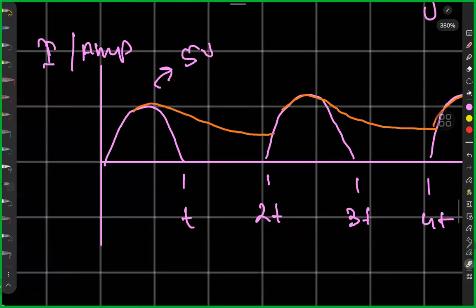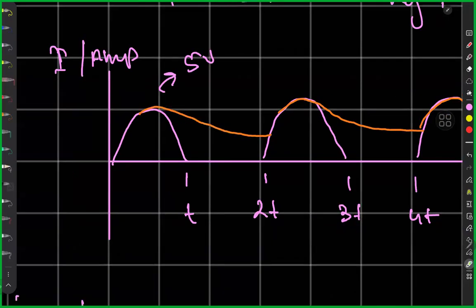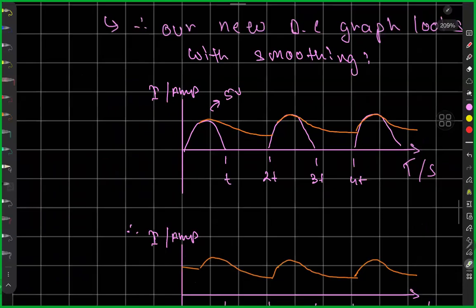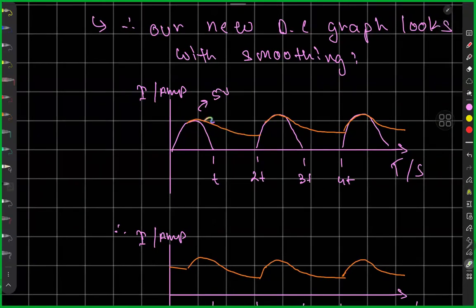And by the way, you will look at this graph and wonder why it is so weirdly shaped. Why is this not more like this or like this? It should be steeper, right? A few people do ask this, and it's a good question: why is this drop not steeper? The answer is that this orange bit that you see is the sum of the voltage due to the capacitor discharging and also the voltage due to the supply. Look, till half T, it's not that the supply voltage is zero. The supply voltage over here, V in, is not zero. It is simply decreasing.